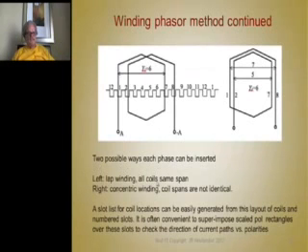The one on the left is a lap winding where the coil span is the same. You see here this is a 6-slot span. The second coil is a 6-slot span. And the right is a concentric winding where you still have 2 coils, you still have the same number of conductors linking the magnet flux. That didn't change at all, but the only difference is how they're connected in the end turns.